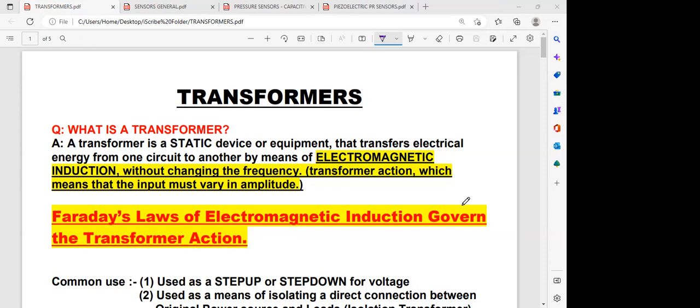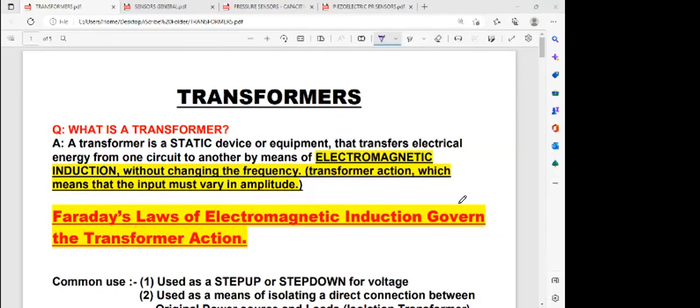If you don't earth your main engine shaft, you can have a current flowing down the shaft, caused by electrostatic buildup of electricity, and that electrostatic buildup is because of your ICCP current. Your shaft is insulated due to the lubricating oil over there.